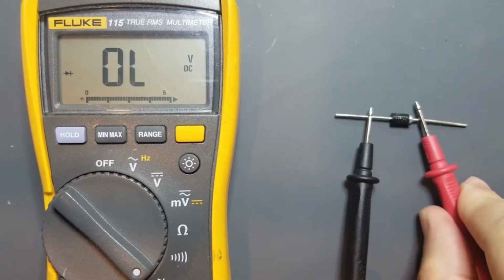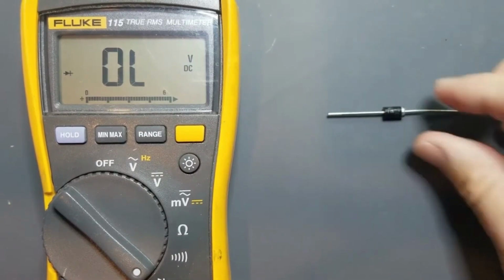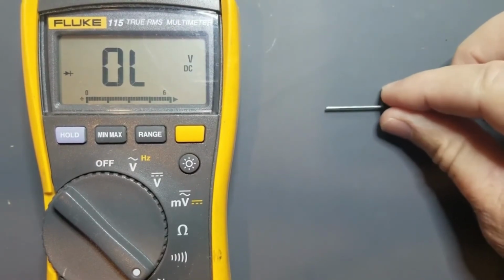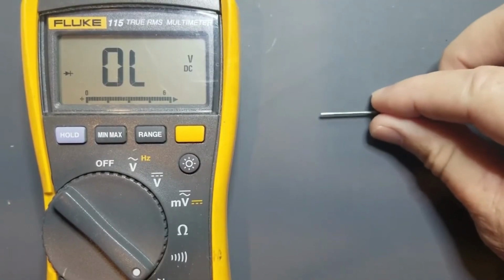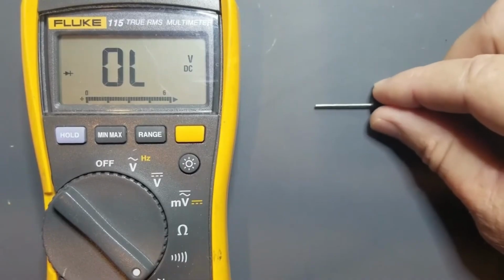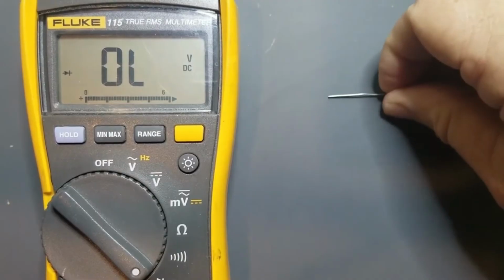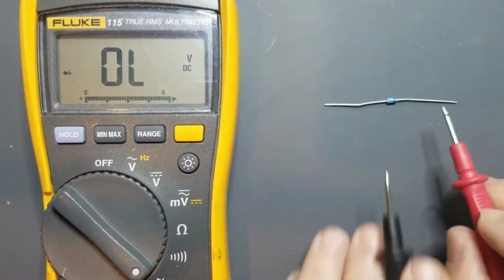Schottky diodes present a lower forward voltage drop compared to standard silicon diodes, typically ranging from 0.1 to 0.5 volts. This advantage reduces voltage loss in power supply designs, enhancing efficiency. Zener diodes necessitate a different testing methodology and cannot be evaluated using standard diode tests.